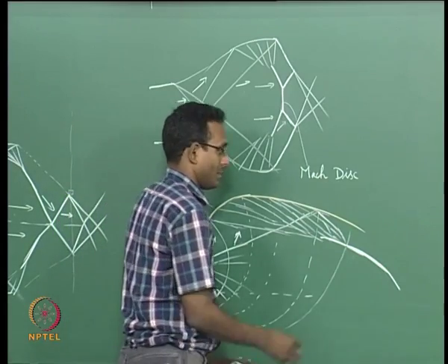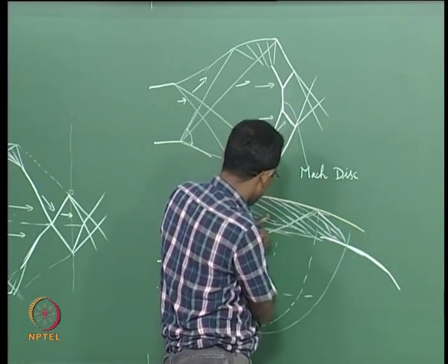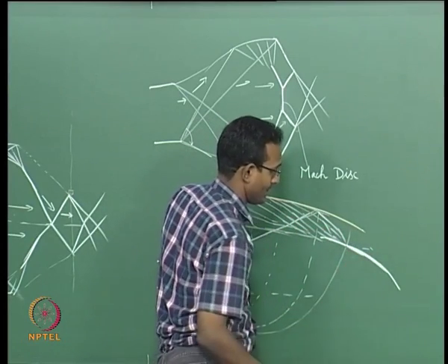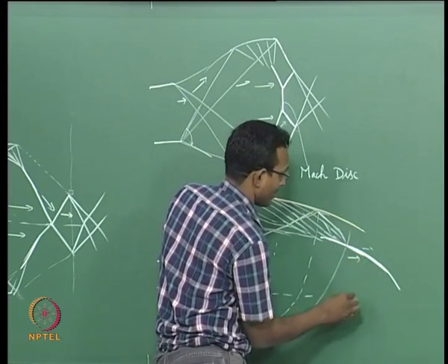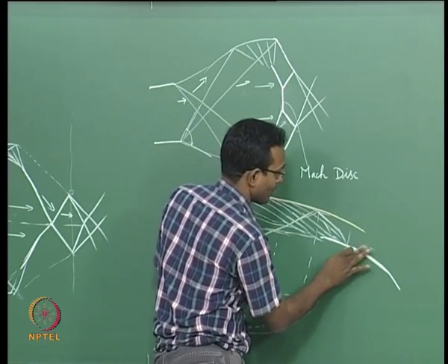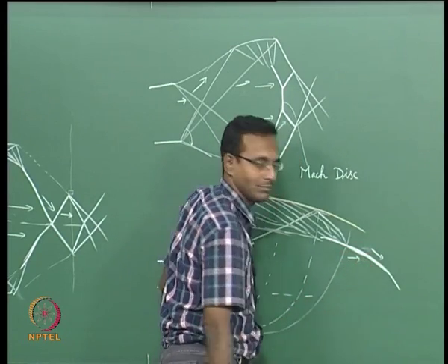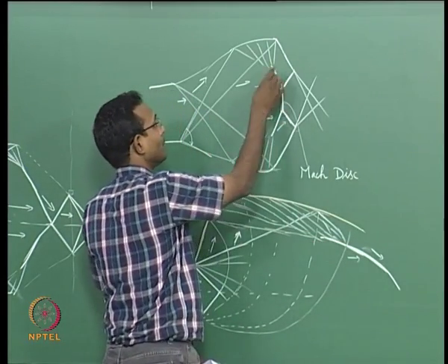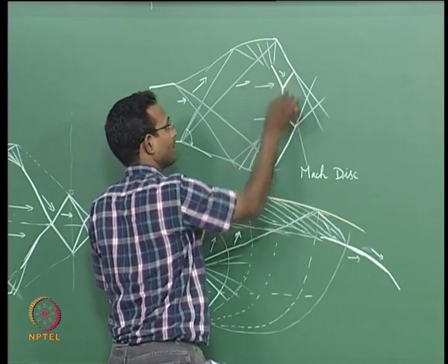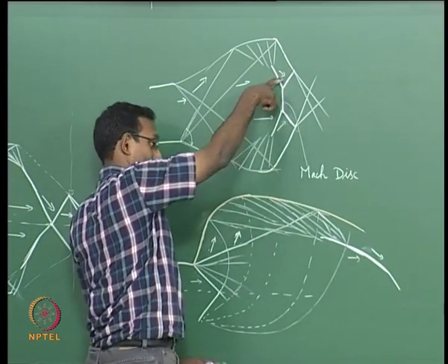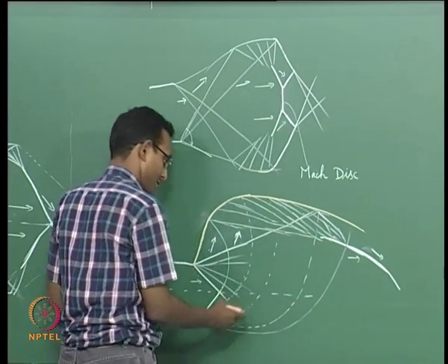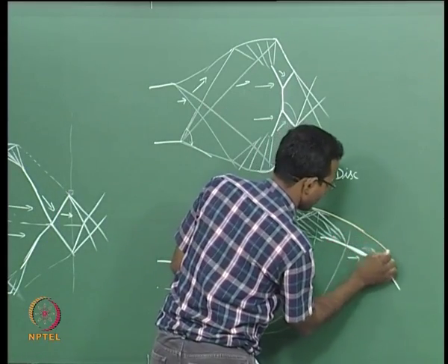Now, the flow as it is coming along this region is going to slowly turn back to parallel before the shock. And after the shock what should happen? It will turn back inward, similar to this, but it is just a more curved shock. Similar to here, after the shock it is going to turn back inward. That same thing is going to happen in this region, and your jet boundary will also start turning like this.